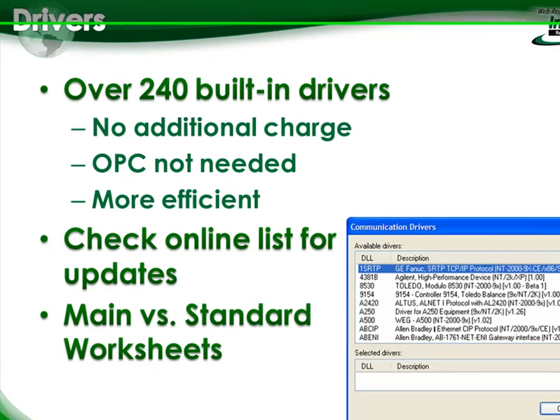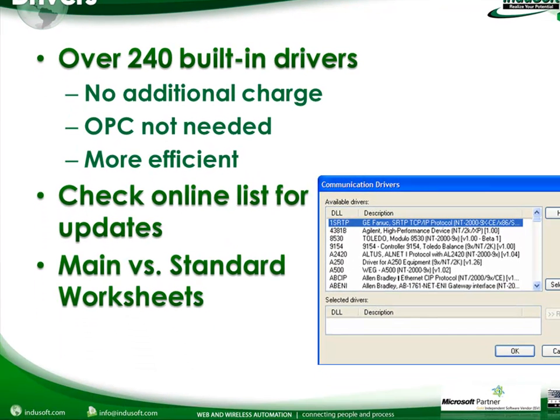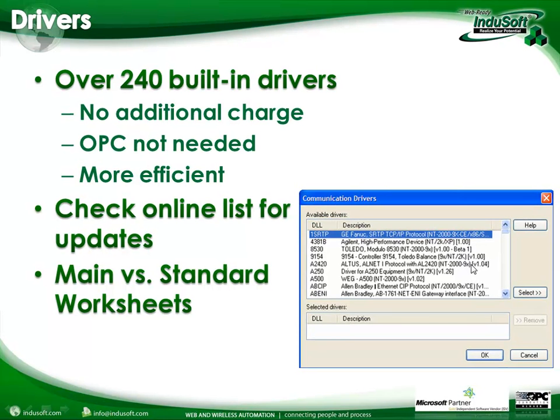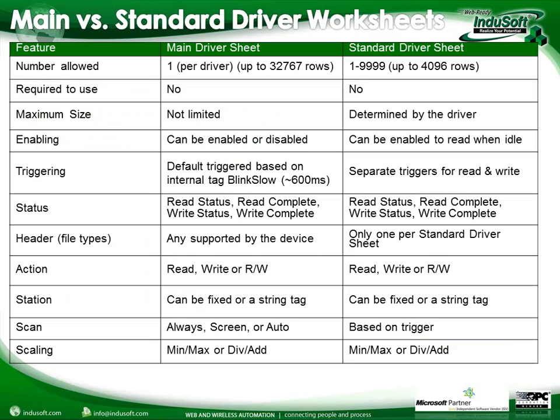So using the built-in drivers is more efficient, and you should always check our website online for a list of updates. It will show you the driver version in the list of communications drivers that we have, and you can always go online to make sure you have the latest version of the driver and that it's updated for your project as you get going. We're going to talk a little bit about main versus standard driver sheets in a moment.